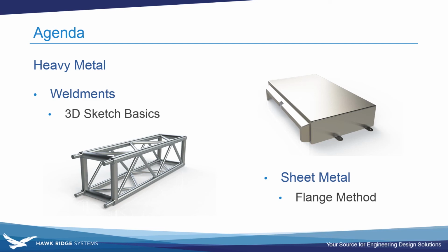All right, the first one that we're going to go over is just some basics of 3D sketching. Perhaps you've looked at that a little bit, and you're familiar with 2D sketching, of course, if you're working with SOLIDWORKS. But we're just going to go over some basic concepts of that and get you going with that. And then I'm going to also talk about some other things that you can do with 3D sketching that aren't really related to weldments.